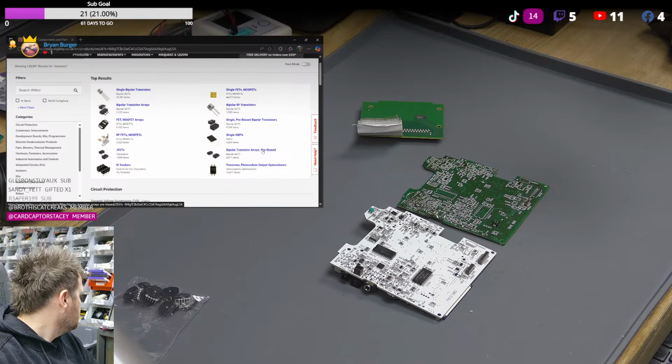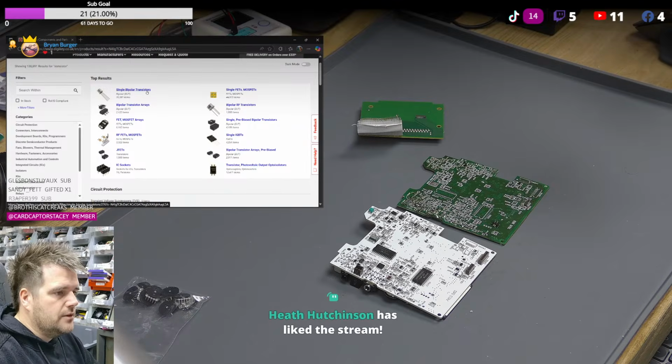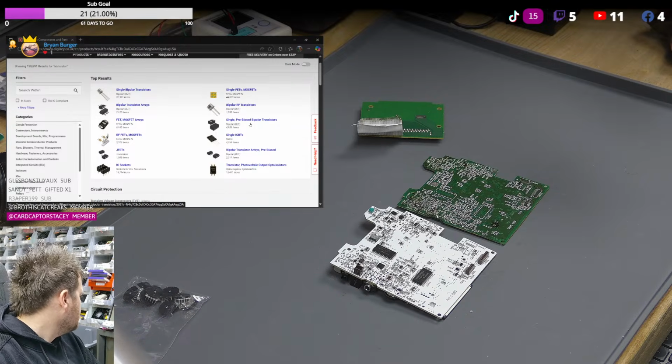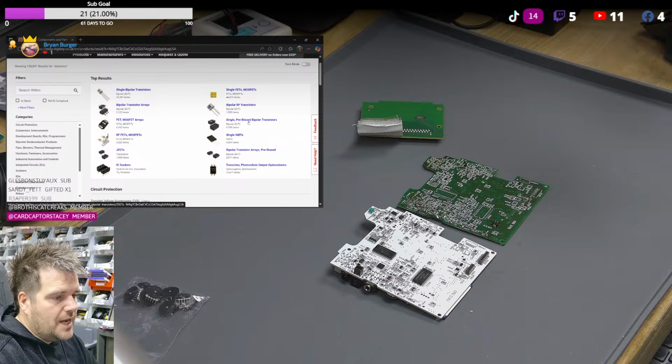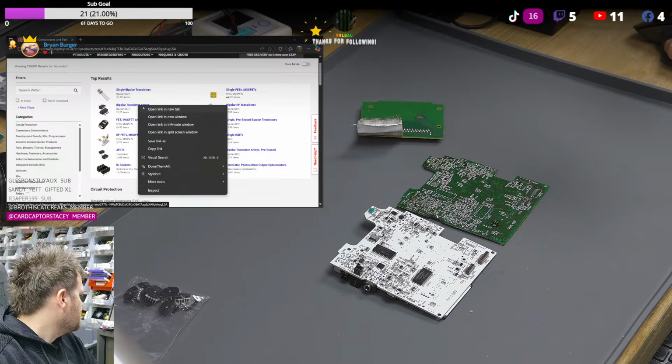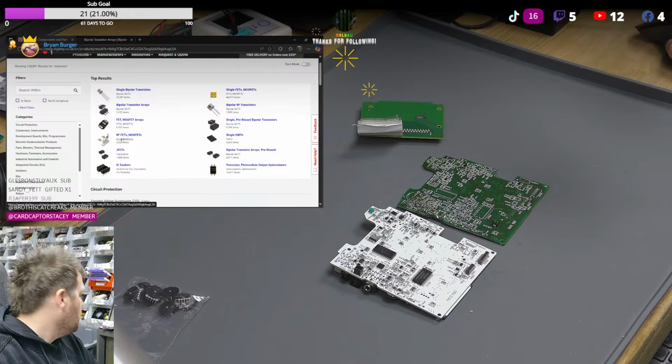It might be that. It won't be single diodes or single transistors because they're 3-pin. We don't care about FET arrays. It's very unlikely. All these are unlikely. JFETs are unlikely. Their sockets, singles, and FETs aren't likely. So the only thing we really have is, it's not going to be a single pre-bias because we've measured 3 diodes. It has to be at least 2 transistors of some form. So we're down to BJT arrays, which are probably just going to be straight arrays, or which it might be,